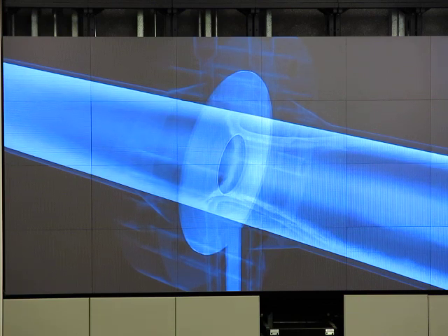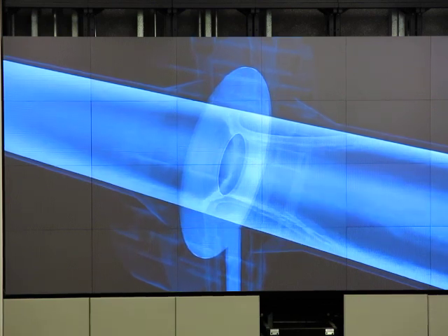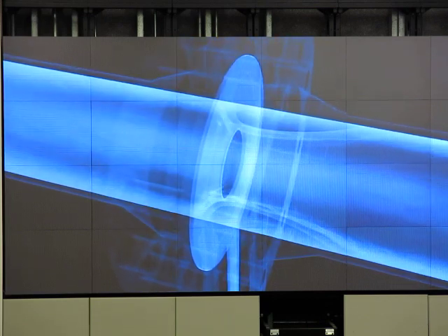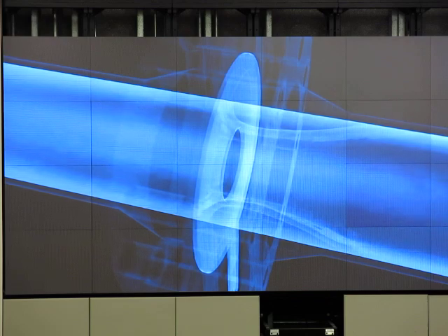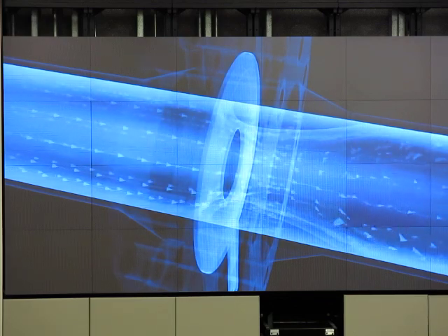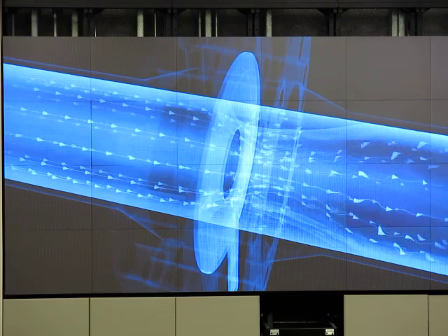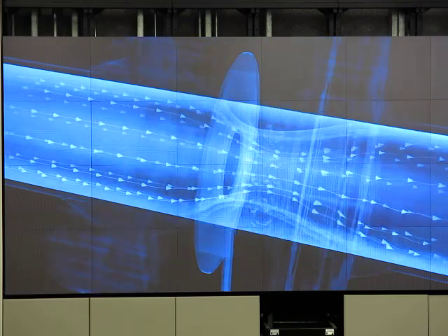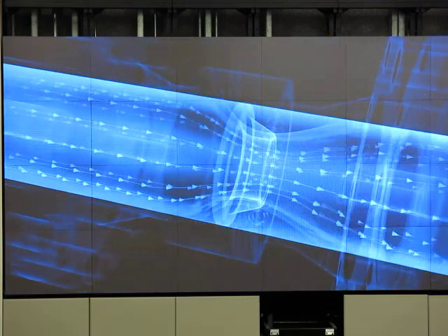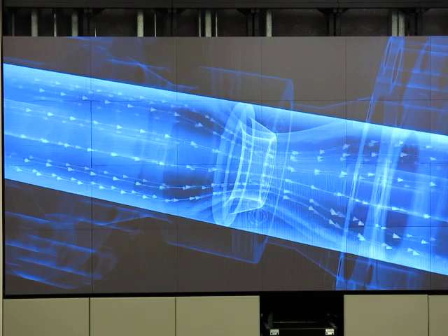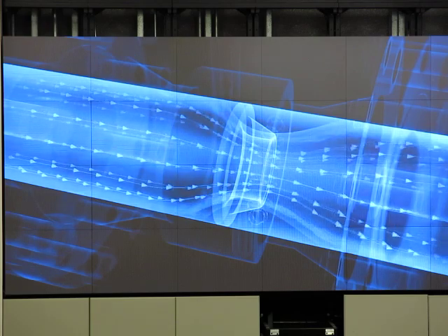However, other designs are available for certain measuring tasks to minimize undesired effects, such as excessive pressure loss or abrasion of components due to solids carried in the fluid. This demonstration shows that an abrupt restriction generates severe turbulence in a fluid. Nozzles with a rounded, funnel-like inlet clearly reduce turbulence and thus create less pressure loss.